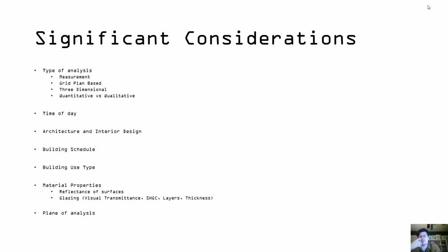But if we're intelligent about thinking about how one uses a space, that work plane may really vary. Sure, people sitting at a cubicle in an office environment, yeah, I buy into that 34 inches. But someone working on an assembly line where perhaps their equipment is elevated, I'm not sure about the 34 inches. Or perhaps they're even working lower.